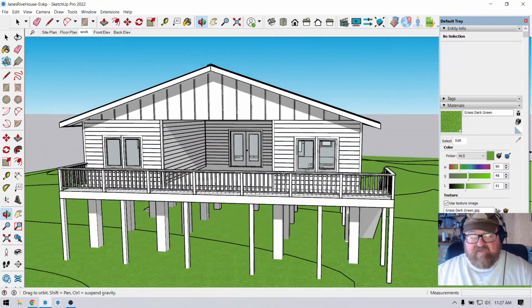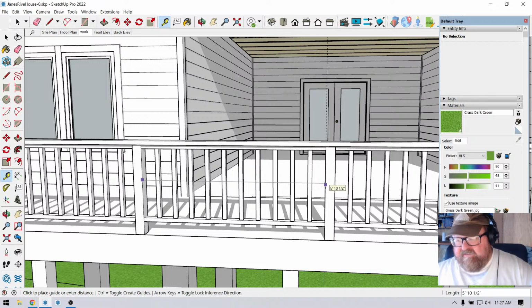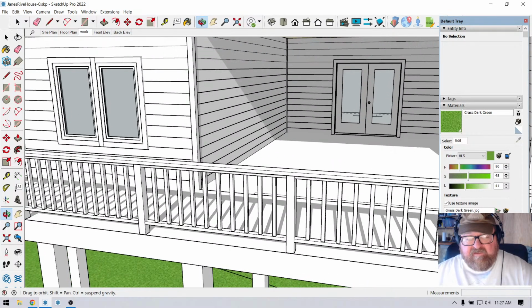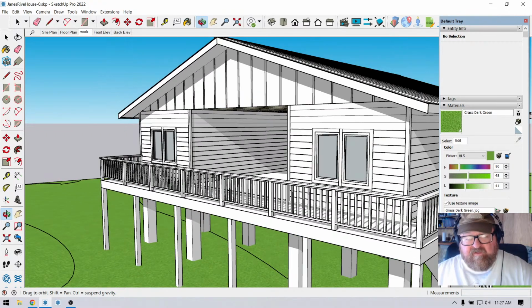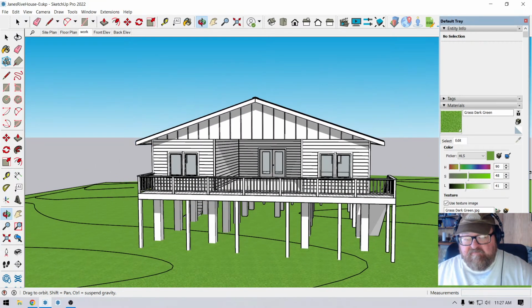Now, one thing I would like to do is see, a lot of times these rails, like local codes, like we can't go, yes, that's too far apart. We can't go, like in Hamilton County in Tennessee, more than 52 inches. Part of that is because the railing has to withstand a 200-pound lateral load, and they've somehow come up with that magic number.